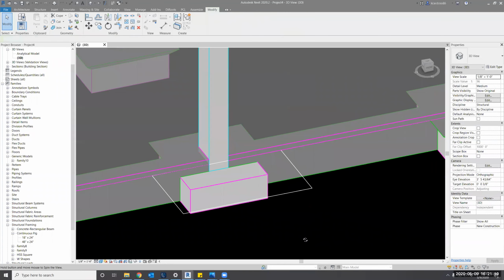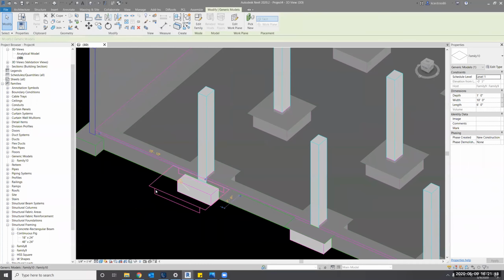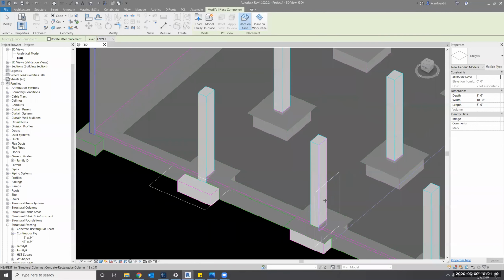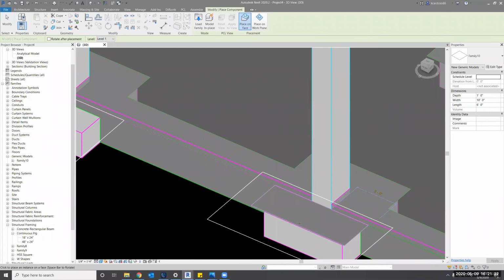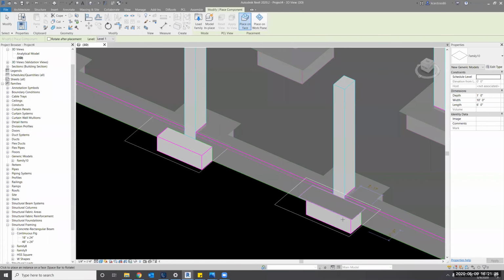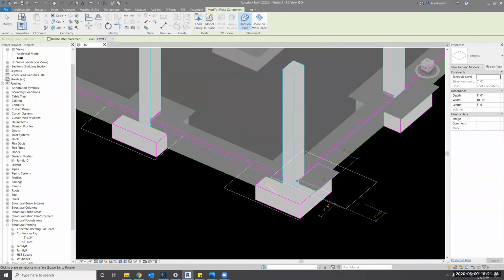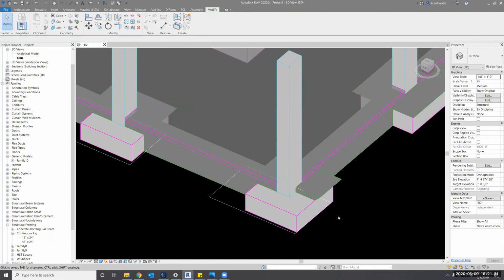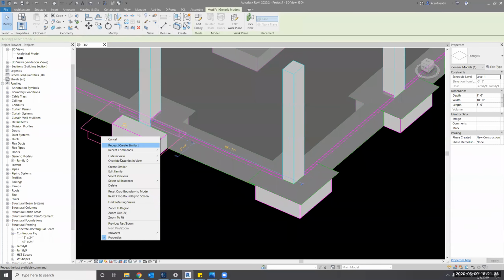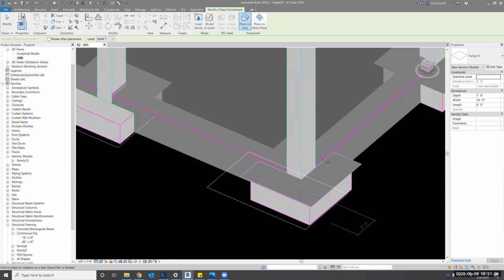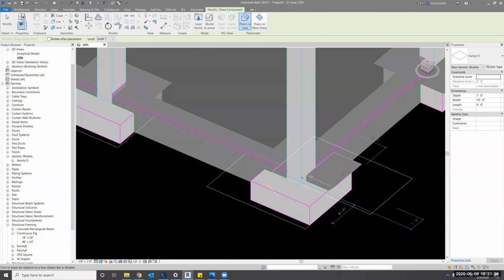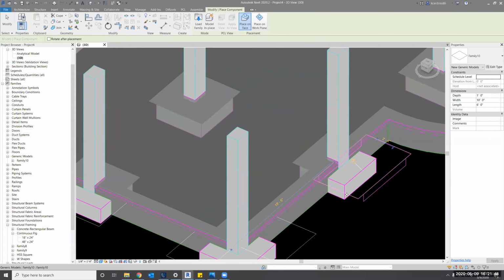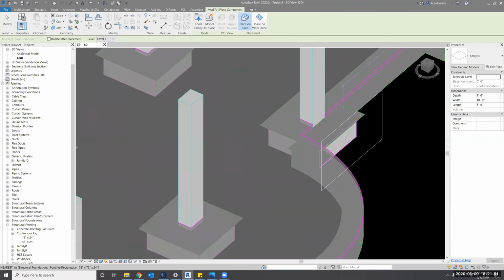We're slicing everything off. So now let's select that void, right click, create similar. It takes on those properties that we set. So now let's hover over this. So what I did there, let's undo. We'll go here and create similar. I placed one here, but then over here, I want to rotate this thing. So you hover over and you hit spacebar on your keyboard, and it rotates. Okay, and okay. And we got this guy as well.